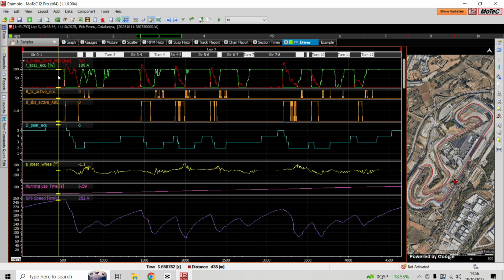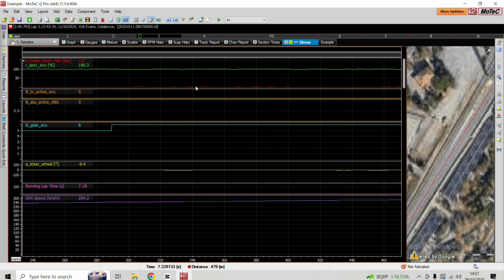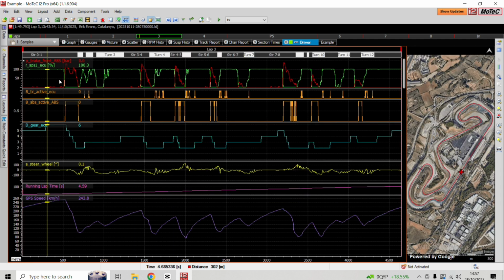And that, first off, is not going to be as efficient with slowing down, but also it scares the hell out of a driver because suddenly he feels like he's got no brake pedal going into a corner. So he's a bit excessive there with his tapping up. It doesn't need to be anywhere near that much, but drivers have little quirks and things they like to do, but that's a bit too excessive, and he will lose a little bit of time doing something like that. So we need to bring that up with them.